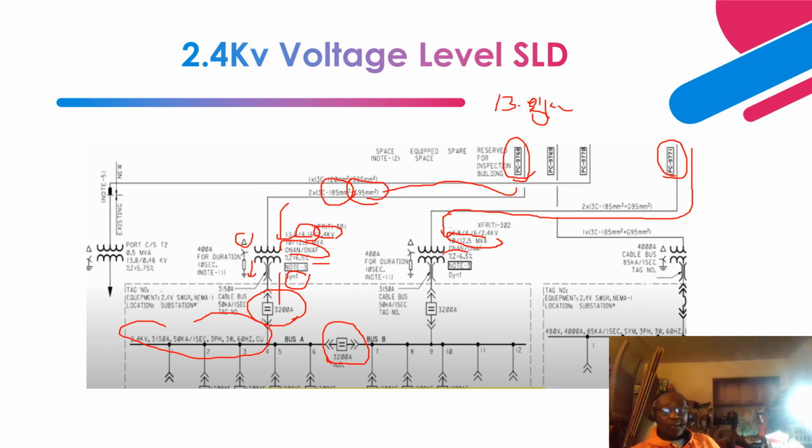Okay, so this is the impedance of the transformer, and this is the vector configuration of the transformer, Dyn1. This shows that the wye side is resistive grounded, and this is the capability of the resistance, right? It can withstand 400 amps for 10 seconds. So basically your ground fault relaying will be set based on this. They've determined that 400 amps is the amount of amperage that can flow within the transformer without causing any damage to the transformer.